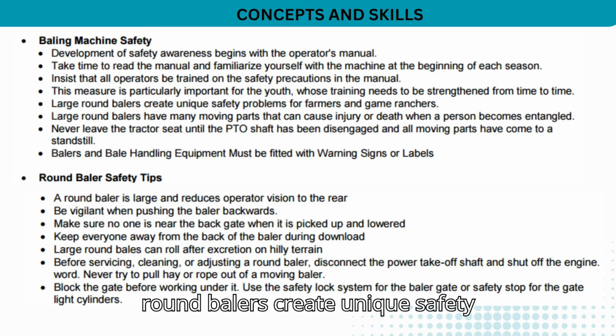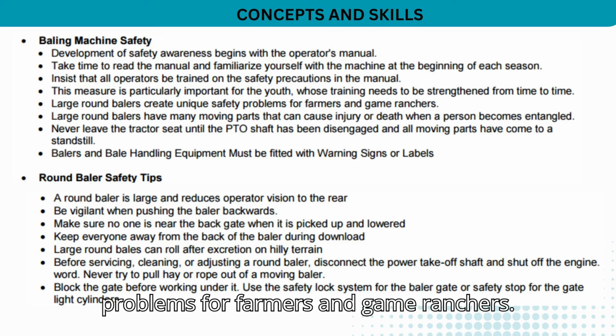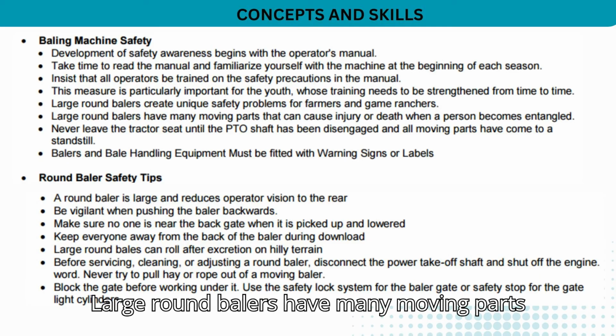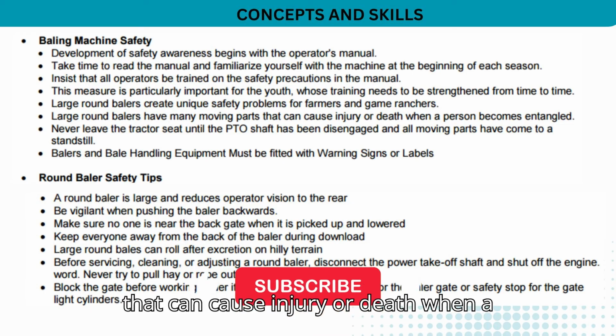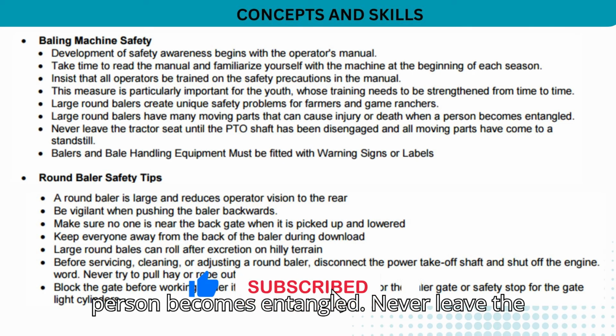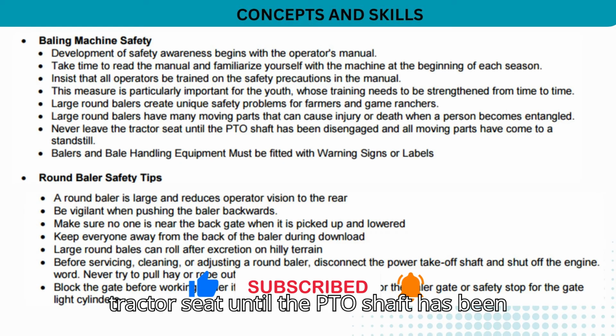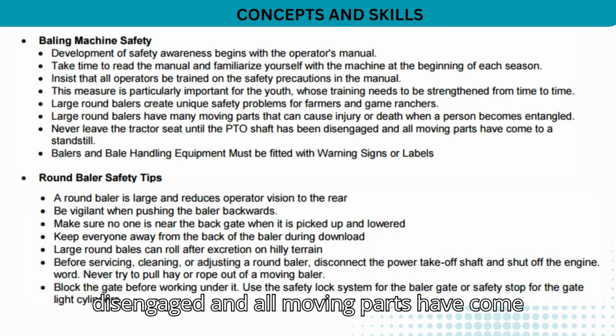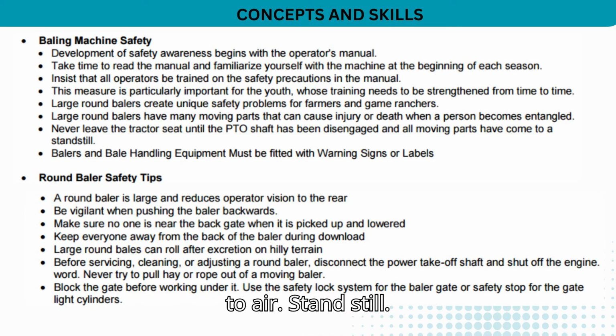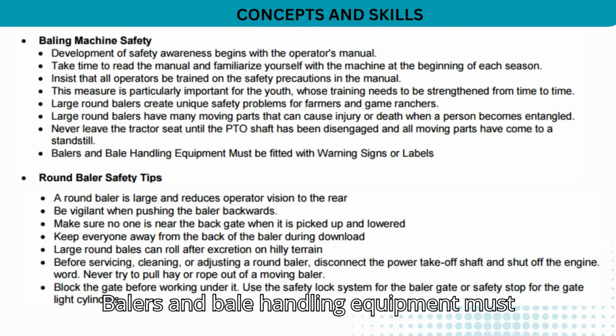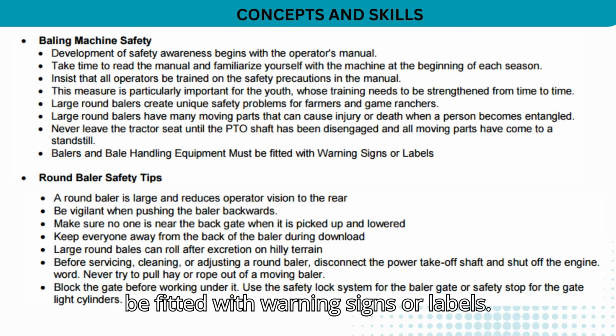Large round balers create unique safety problems for farmers and game ranchers. Large round balers have many moving parts that can cause injury or death when a person becomes entangled. Never leave the tractor seat until the PTO shaft has been disengaged and all moving parts have come to a standstill. Balers and bale handling equipment must be fitted with warning signs or labels.